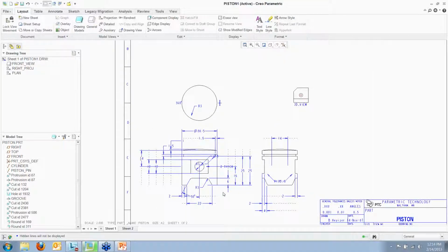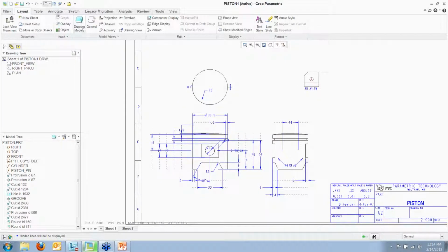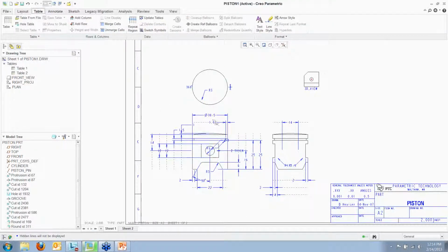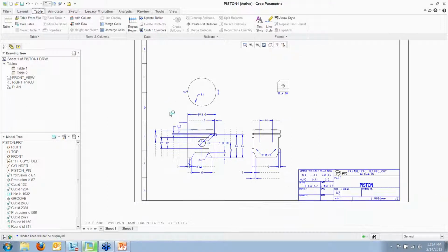Well, you'll notice in Creo 2, that issue has been resolved. I got lots of complaints about that, especially in my intro classes that I teach, with people sitting there for 5 minutes trying to figure out why they can't pick an annotation. Now, no matter which tab I've got selected, I will be able to pick an annotation without having to hold down the Alt key.